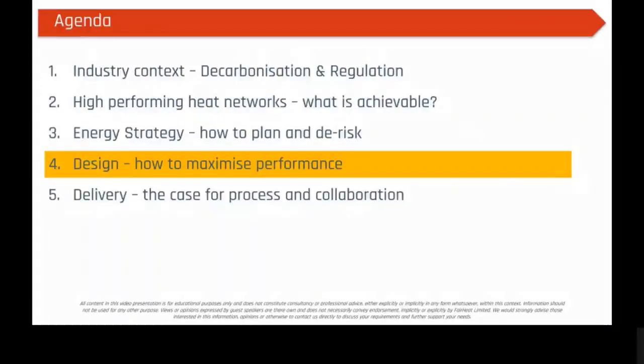So that's energy strategy. As I said, a big change for the industry, a lot of uncertainty, and quite high risk, in that you can suddenly find your per dwelling or per building cost profile of a heat network go through the roof. But thinking through the right strategies, thinking about hybrid systems, can be a clever way of working through that uncertainty and finding a way to transition to heat pump technology, rather than jumping off a cliff and suddenly finding yourself doing 100% air source heat pumps on a scheme where you've not done it before. So think that through carefully and advise your clients accordingly.